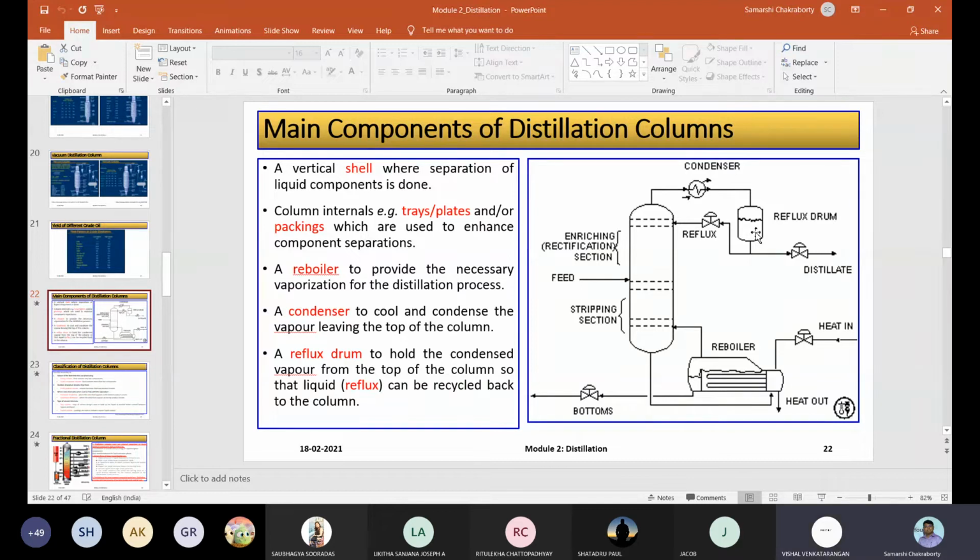Yes, sir. Yeah, that is what I wanted to say. That you understand now. If I close this, I have to open this. Or else there is going to be differential pressure, and too much liquid hold up can take place. Then you have to open this distillate valve and let more and more distillate be produced. Okay, understood. Let me just go back to the slide.